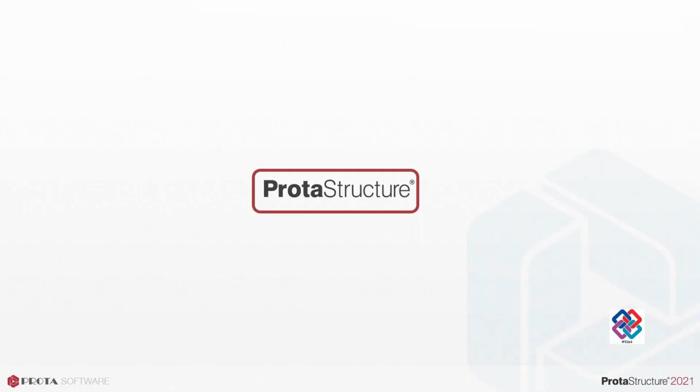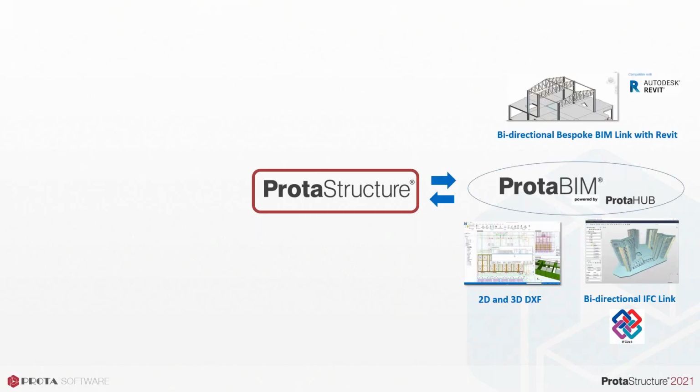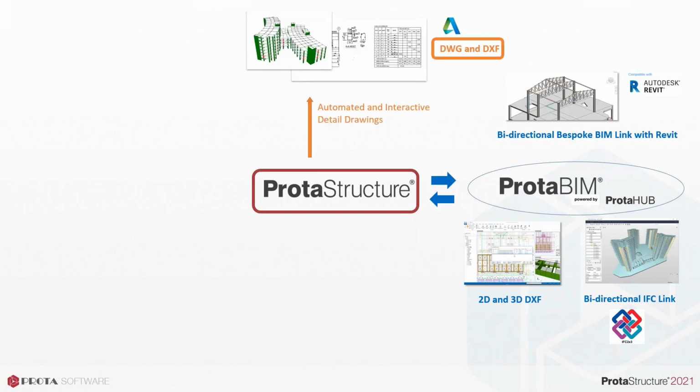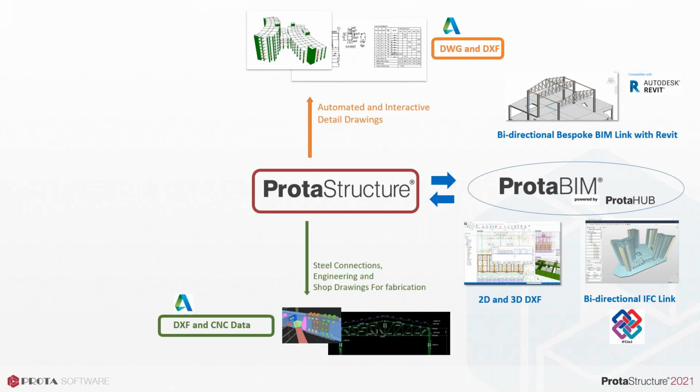Okay, ProtaStructure. With ProtaStructure, you can model, analyze, and design multi-material building structures using a structural BIM model. Then this BIM model can be shared to different BIM platforms like Revit. And after you're done with your design, the reinforcement details can be automatically created using Prota Details. Then the design can be pushed to ProtaSteel for connection design and fabrication purposes.